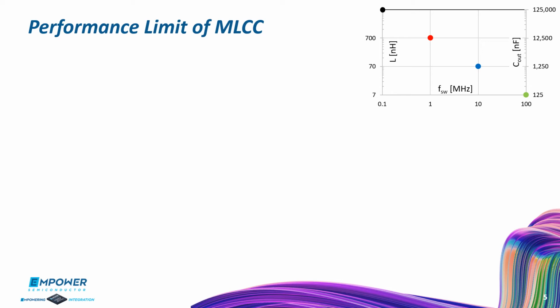Let's consider a simple example. For a 10 millivolt output voltage ripple target, depending on the switching frequency, say from 100 kHz to 100 MHz, the LC filter can be realized with various combinations of inductance and capacitance values. Here I have selected 4 pairs to constrain the inductor current ripple within 1 amp.